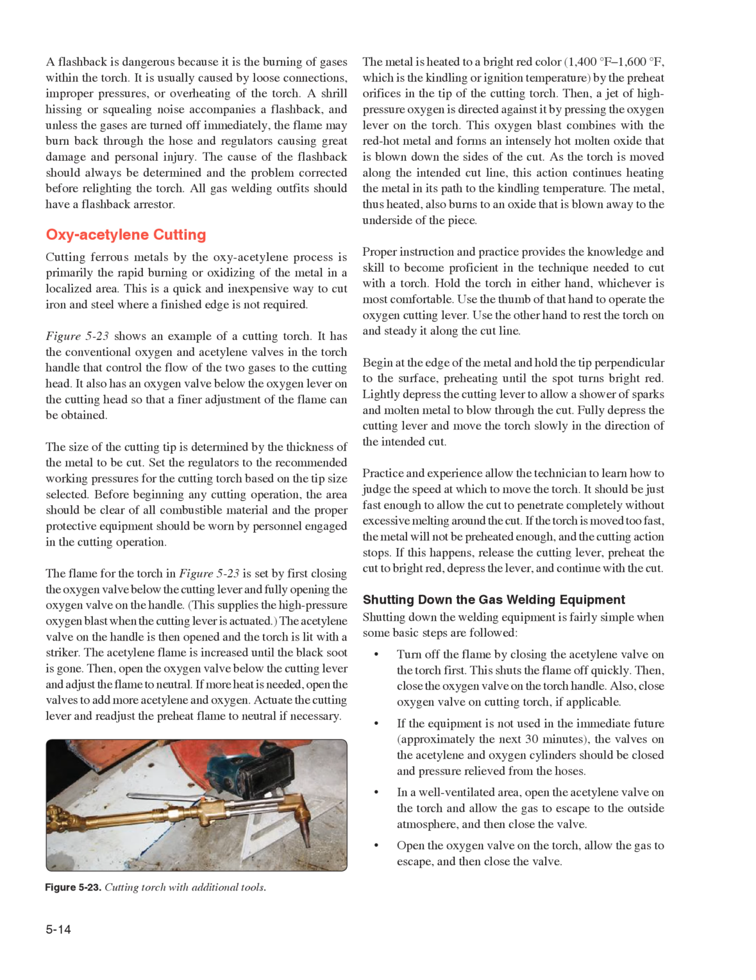Practice and experience allow the technician to learn how to judge the speed at which to move the torch. It should be just fast enough to allow the cut to penetrate completely without excessive melting around the cut. If the torch is moved too fast, the metal will not be preheated enough, and the cutting action stops. If this happens, release the cutting lever, preheat the cut to bright red, depress the lever, and continue with the cut.